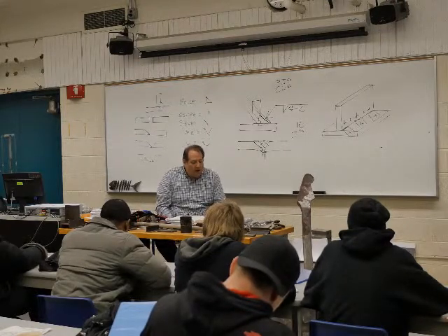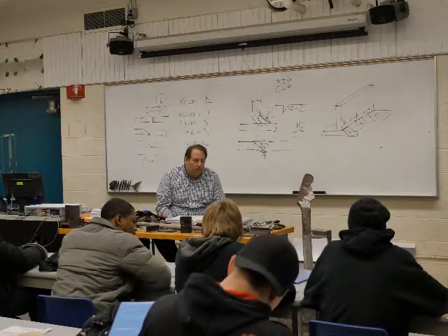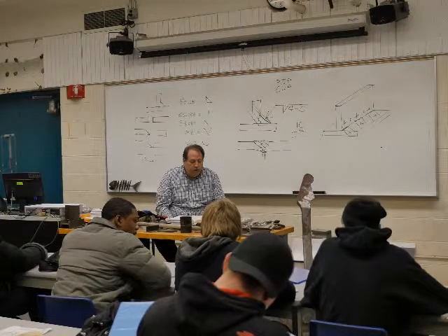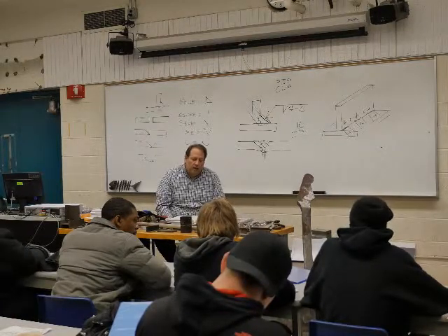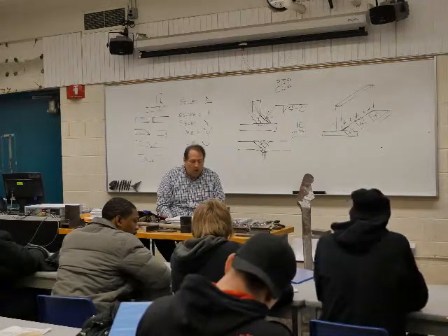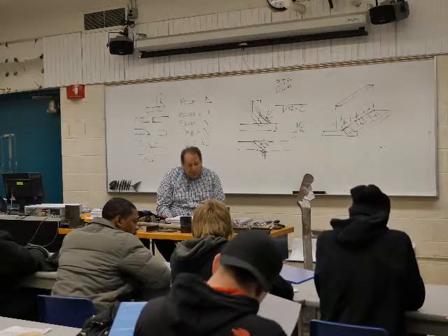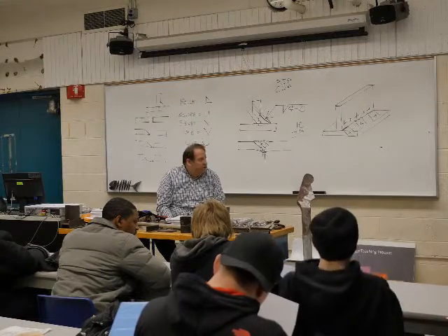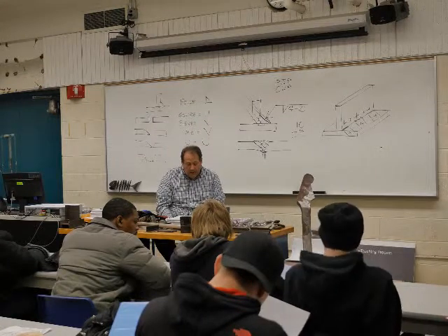So we did the types of welds. We did fillet, square groove, V groove, bevel groove, U and J groove. We did talk about plugs and slots, nothing big there. We got field weld, weld all around, concave, convex, and flush. And then we did go into the finish symbols on that too.